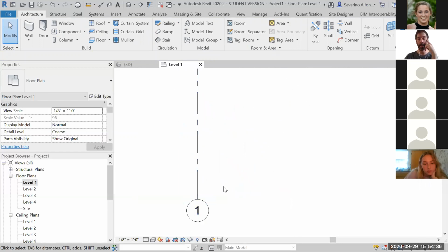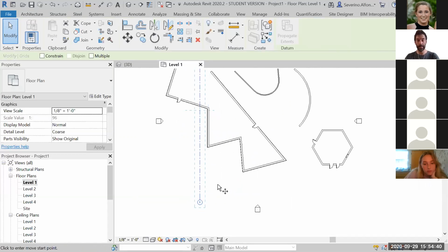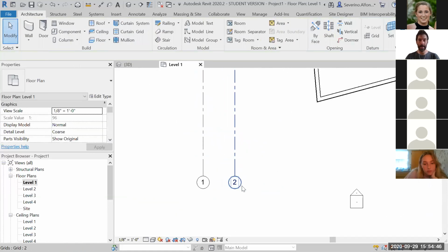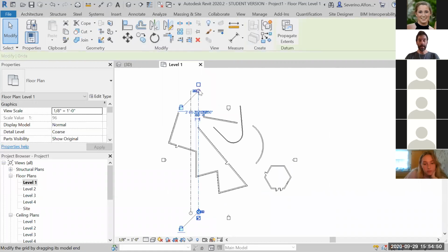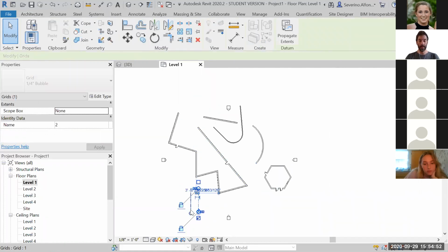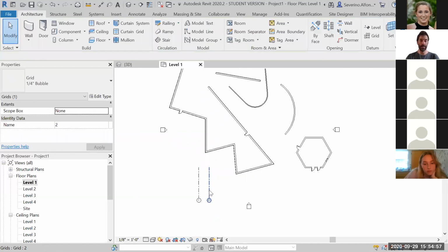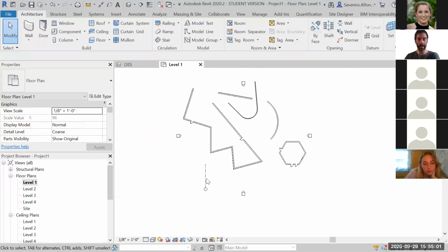Grids are automatically named or numbered, and you can definitely copy them and place a number, like, let's say 10 feet to the right, and then it will be renamed automatically. You can adjust the grids in different ways. There's a whole world of grids and how they work and so on. I'm gonna delete those.